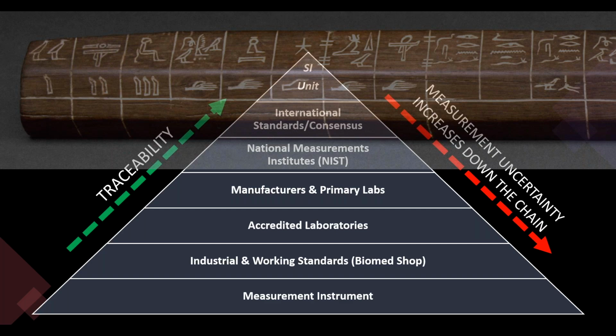Its uncertainty is about 0.072. And then we have our Keithley digitizing DMM here. This has the ability to measure temperature down to 20 millikelvin, and with the SPRT with it, we're looking at about 45 millikelvin. So each one of these has a different accuracy and different response times.